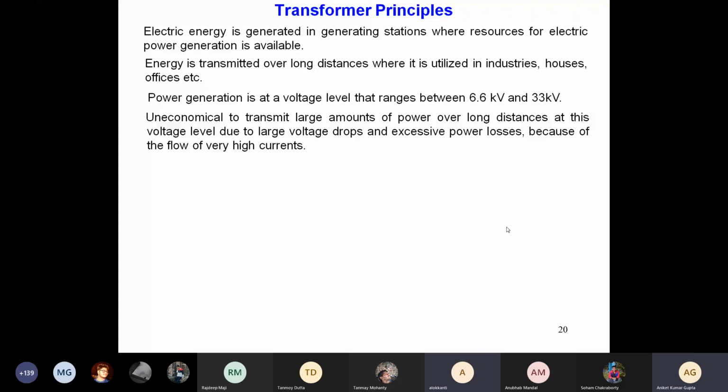If you have real resistance, the more impedance you have, there will be more drop. If your distance is more, then your impedance values will also be more. The wire will have some resistance and some reactance, and it will increase because it is directly proportional to the length. R is equal to rho L by A; if you simply consider resistance, it is directly proportional to the length.